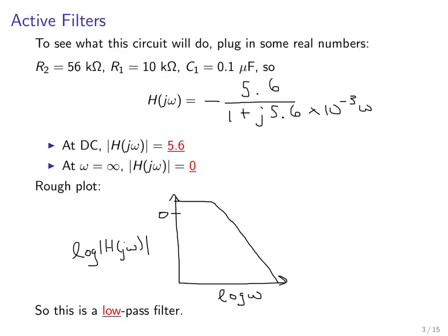And we have, again, these three regions. We have zone 1 here, that's the pass band, the frequency components that will be passed. This is zone 2, the corner region, and then we have zone 3, or the stop band, on the right. Now the main difference between this transfer function and a passive transfer function is that in the pass band we can have a gain now that's greater than 1.